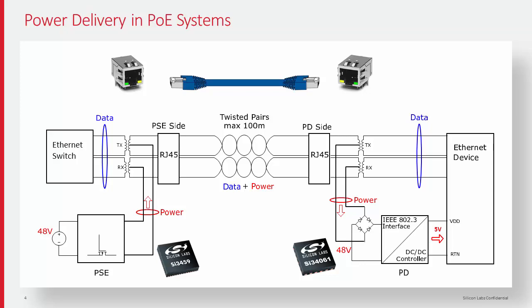So, a little bit more in depth. The Ethernet standard is a bipolar signal, so it's a differential signal. What Power over Ethernet does is take the common mode of that differential signal and apply a fixed DC power across the Ethernet cable so that it can deliver energy from a big network switch to a smaller device at the other end. So that's the general perspective: taking that differential signal and riding on top of it with some DC voltage. I see.